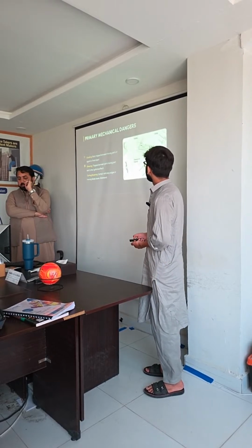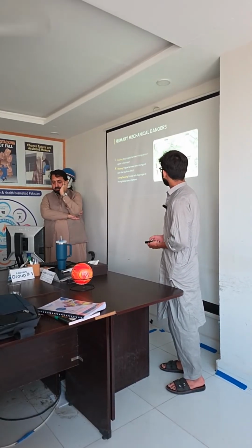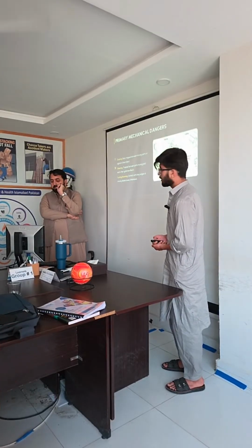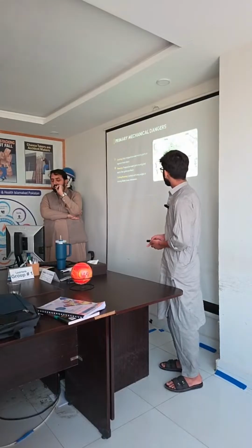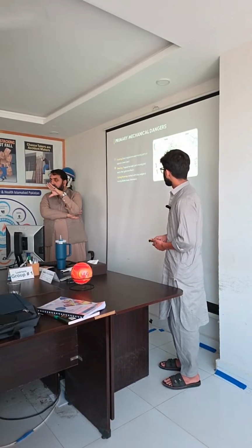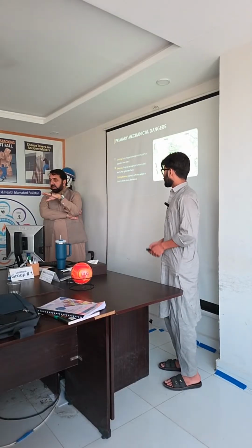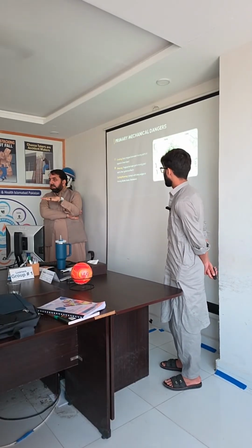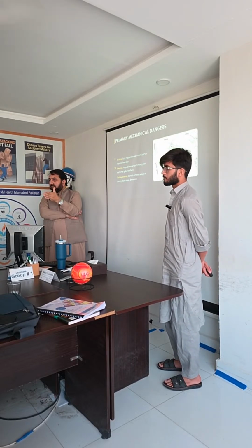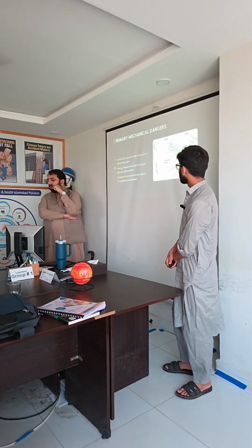Primary mechanical dangers: crushing, body trapped between moving parts or against a stationary object; shearing, trapped between parts moving past each other. These are types of injury. Yes. What is the difference between mechanical and non-mechanical? If you touch a machine and it hurts you, okay, it is mechanical. Non-mechanical is the auxiliary, like dust, vibration, particles, so this is called non-mechanical. So we are seeing accidents due to the mechanical